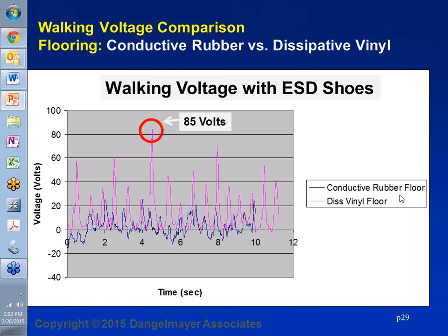There's another related question. How do you feel about using ESD waxes versus conductive rubber or dissipative flooring? The ESD waxes or finishes work surprisingly well, and they also are low charging and work effectively even on non-ESD flooring underneath it. But it requires a lot of maintenance and comes with its own headaches. Typically, when there's a problem with ESD wax, the root cause circles back to the application and errors made during application.